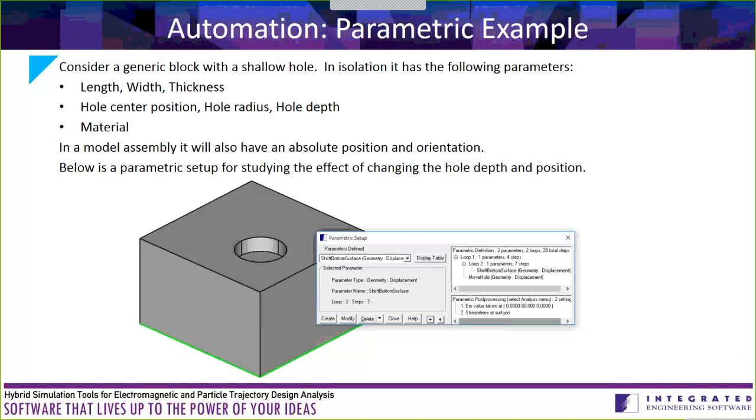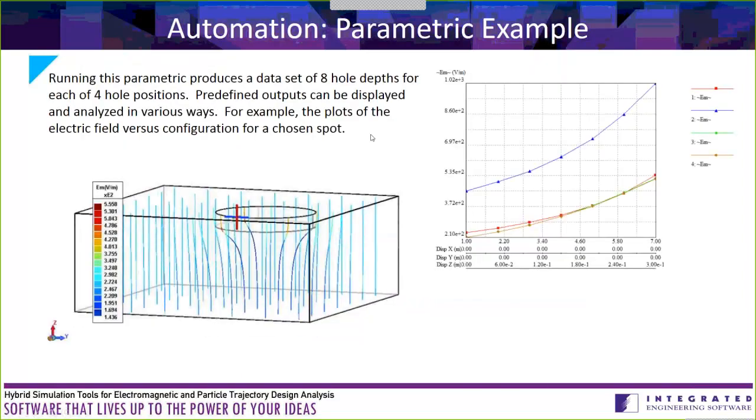Parametrics are a way that we have of automating when your model is defined and you simply want to run variations on the model. The new thing for us with parametrics, and existing users will recognize we've been able to set up this kind of systematic study for many years, is that for this region, where I've defined what I want to get out of all the variations that are going to run on this model, there's a good argument for doing this part with the define outputs instead of defining it in the parametric itself.